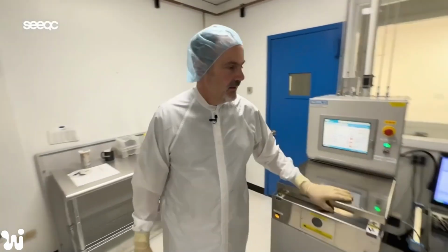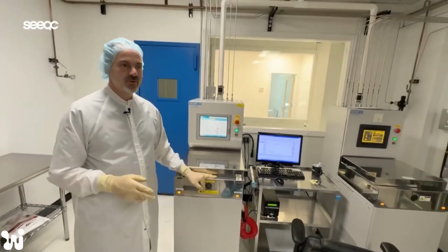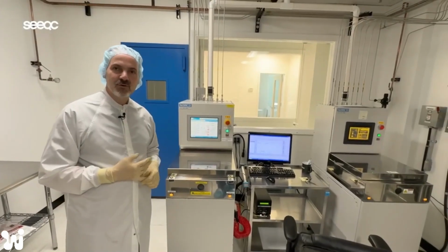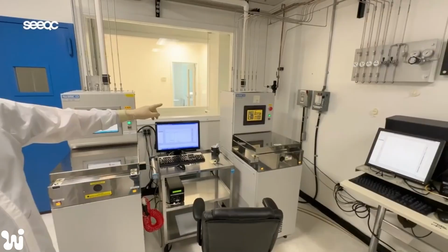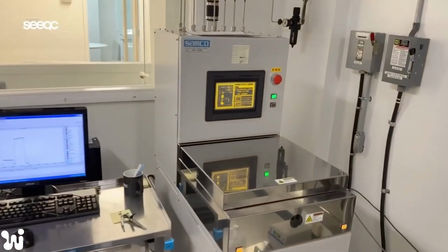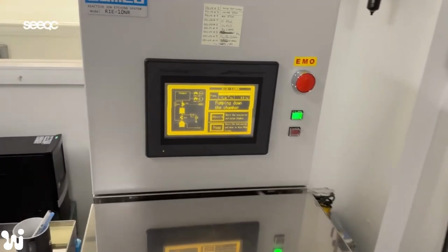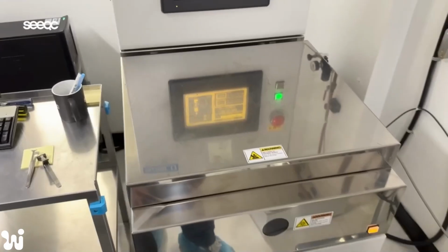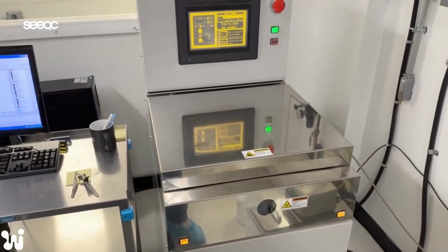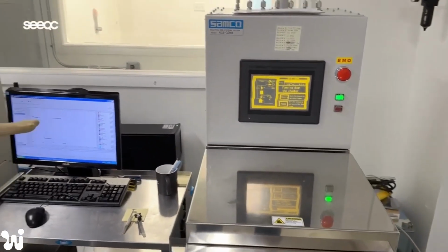This is a plasma lab. 3 of the tools here are used for etching. One of the tools is used for deposition. These tools are reactive ion etchers used for etching. This is a metals tool. We etch molybdenum, niobium, titanium, tantalum. That's all done in this tool. We use sulfur hexafluoride, SF6, or CF4 to etch all the metals here.